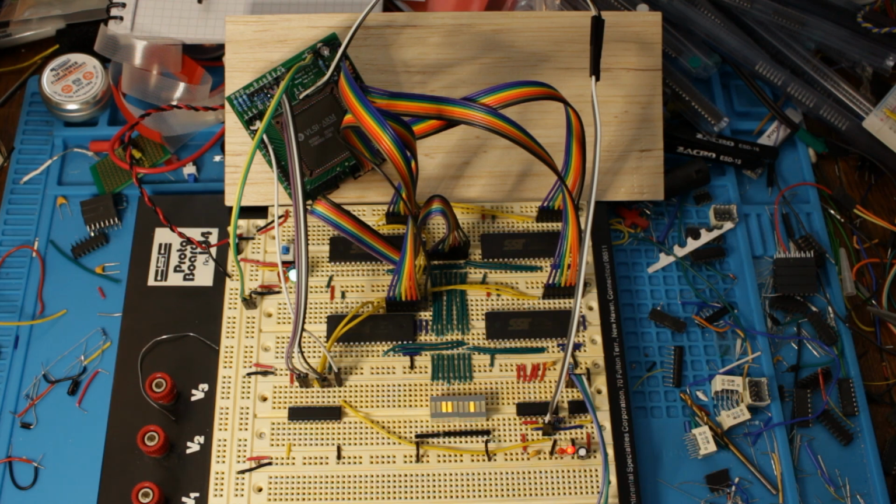So what we're expecting to see here is an opcode fetch followed by a read from the memory location 4 bytes ahead of where the opcode was, and then a read from the memory location another 4 bytes ahead. And these are opcode prefetches for the following instructions, because the ARM doesn't know yet that it's not going to execute them. And then once it's done those 3 reads, we should see it then jump back 12 bytes.